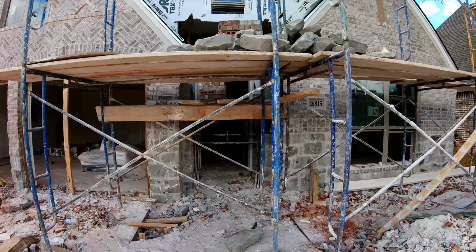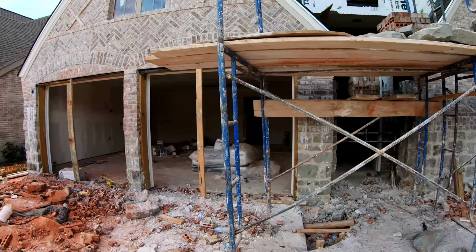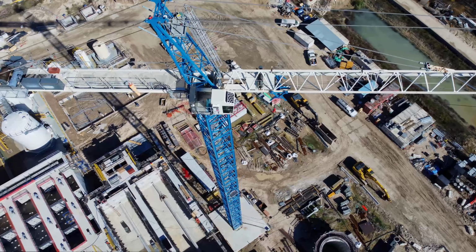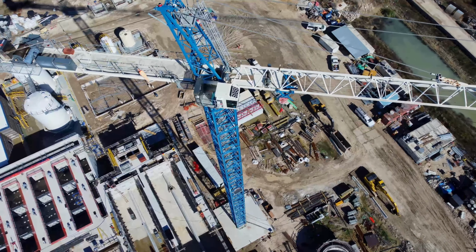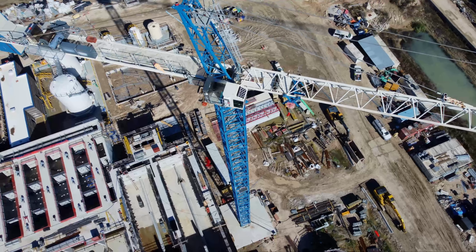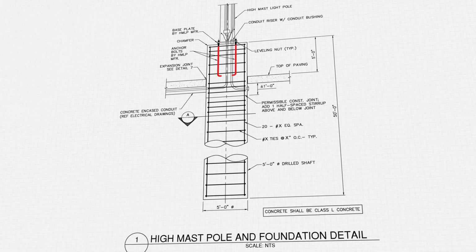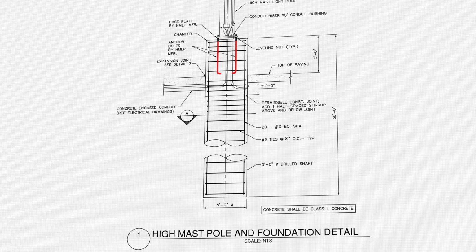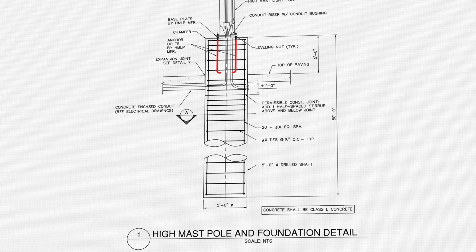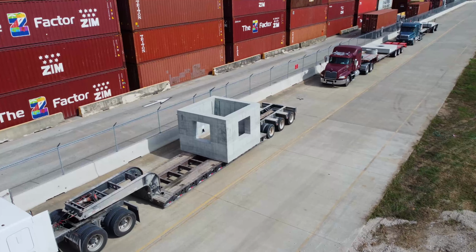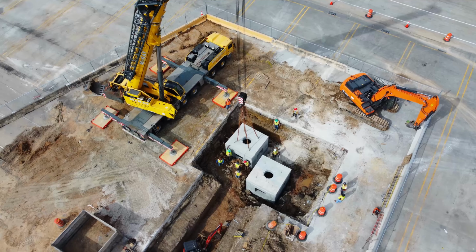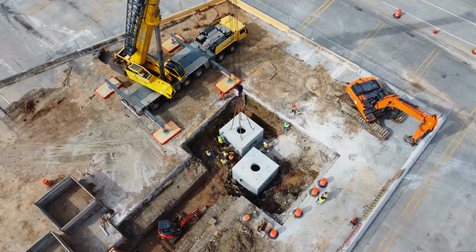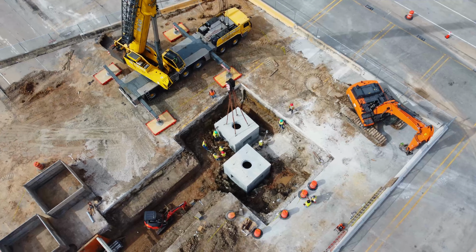Architectural divisions. These divisions cover architectural aspects of any buildings that are involved in a project. Structural divisions cover structural details of the civil and architectural divisions. For example, the civil drawings may show that a light pole is needed at one point. Foundation details for the pole would be in structural divisions. Manholes may be required here and there. Details for manhole construction would be in structural divisions. So you got an idea how it works.